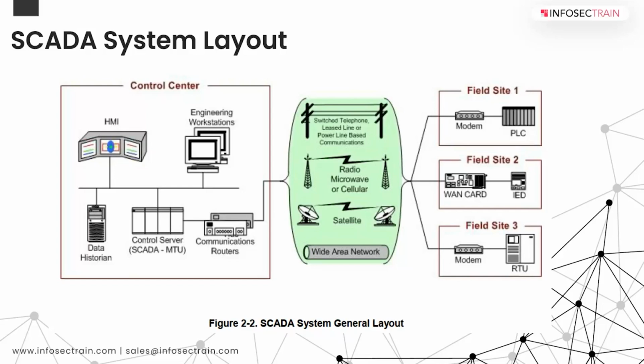Originally, this remote access capability was allowed basically to help operators sitting in the control center do some remote diagnostics, repairs, or monitoring, usually over a dial-up modem. Nowadays, we don't use dial-up modems. There are 4G modems available, and there are secure ways of doing a remote connection.